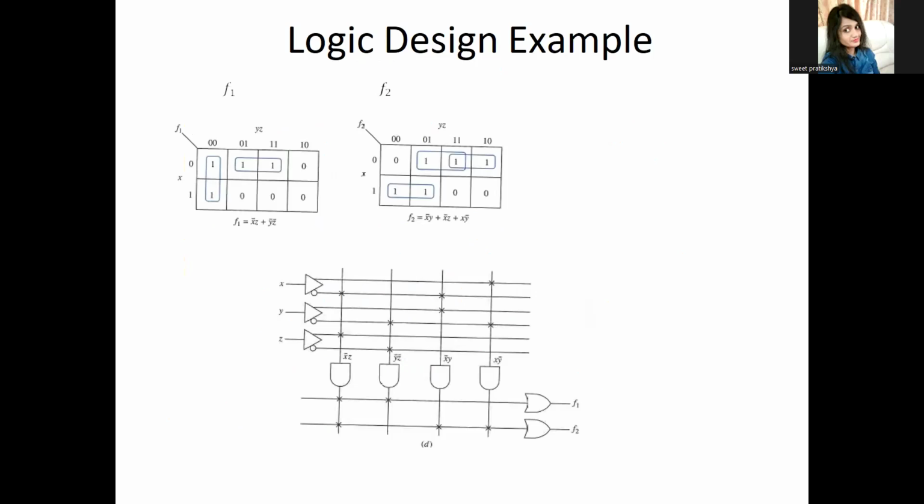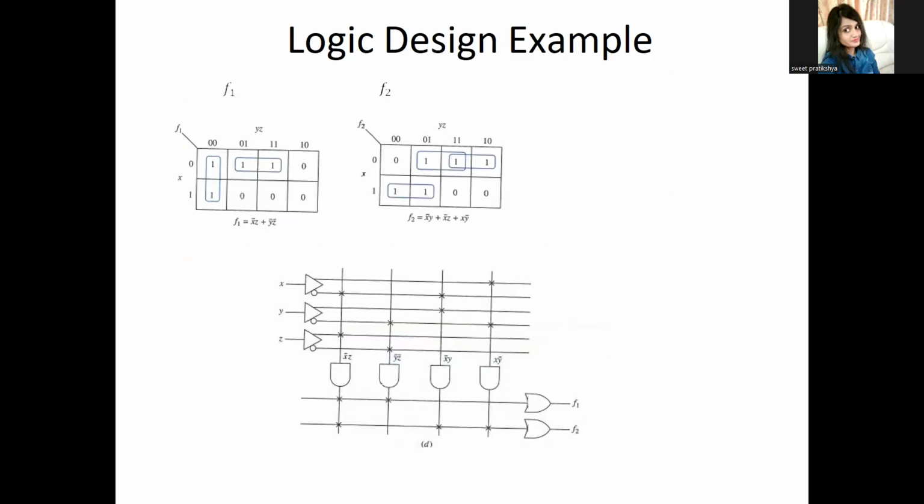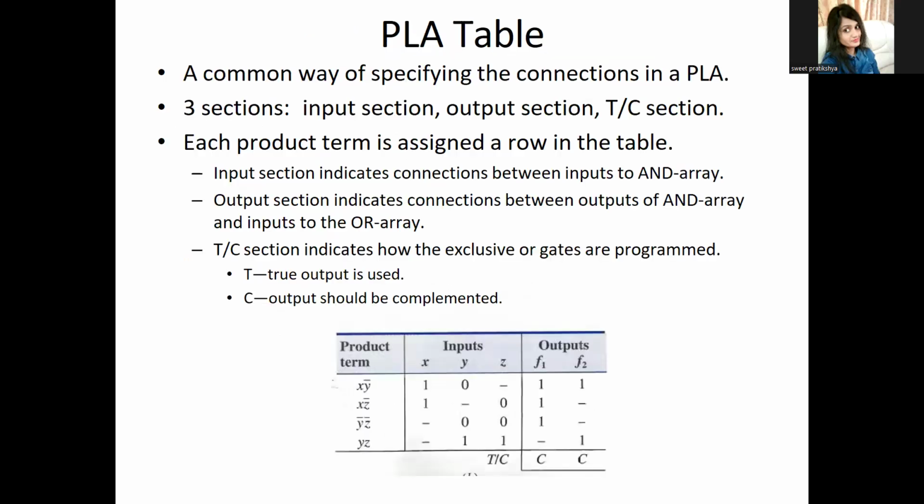This is a simple logic design example, where this slide shows an example logic function using a PLA. You can see how inputs are connected to the product terms using AND gates, and those are summed through OR gates to create the output. Including complementary variables, we can reduce the number of product terms needed.